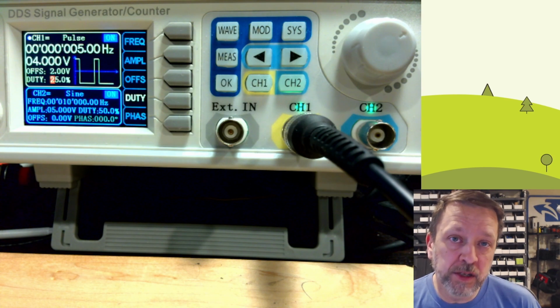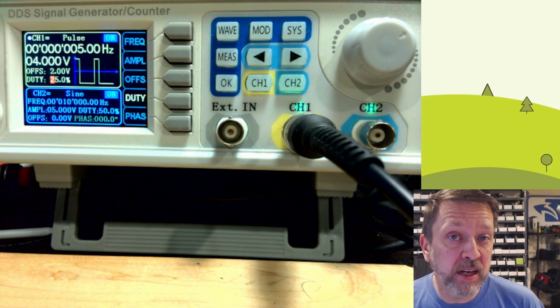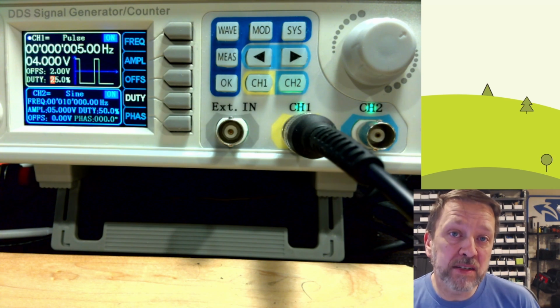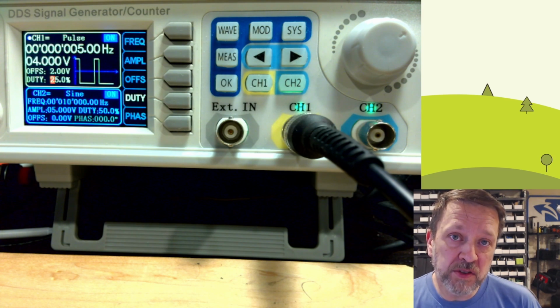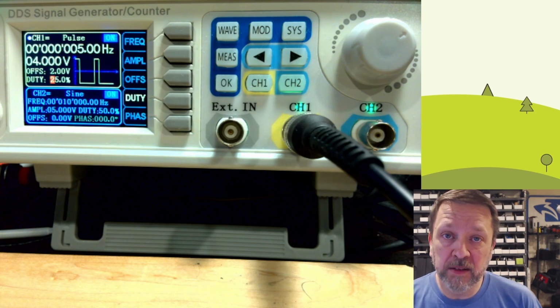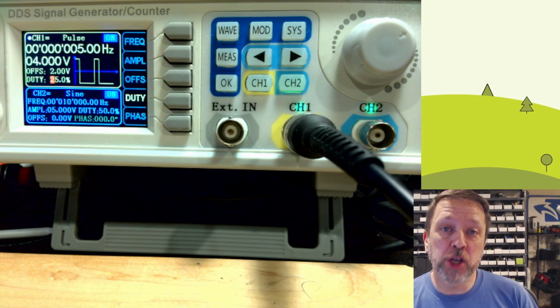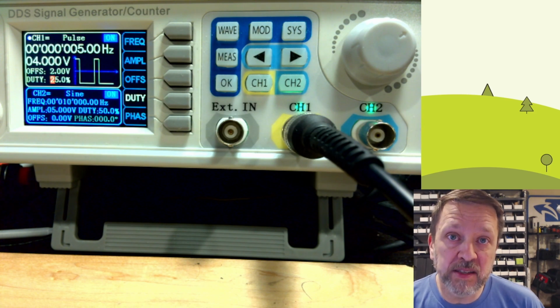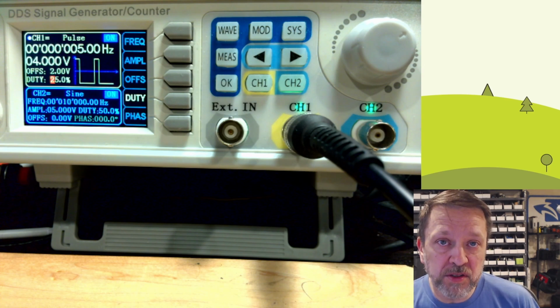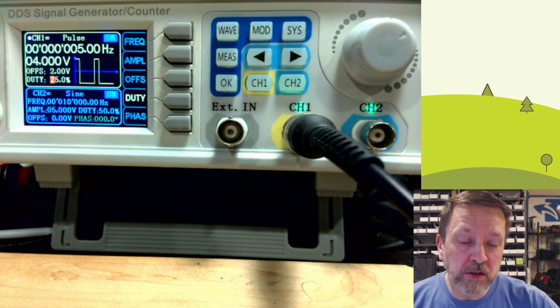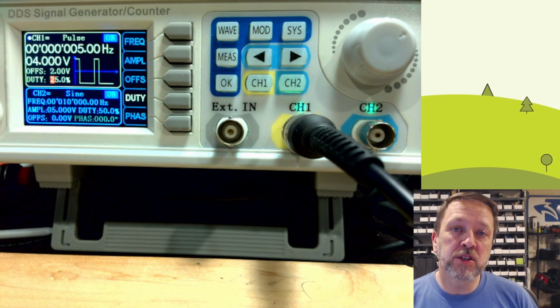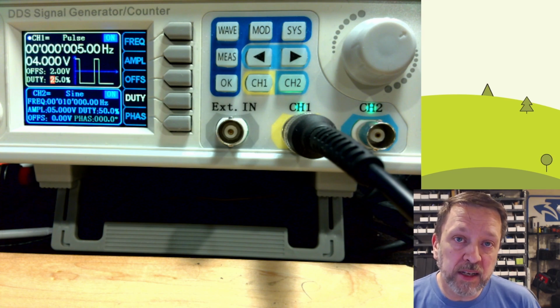Maybe I have an application that I need to handle button clicks, and I want to see how fast I can service those button clicks. How fast can I read data coming in? There are sensors that provide pulses for data, an anemometer, so for checking the wind. Basically, as they spin, they give a certain number of pulses per second, equating to a certain wind speed. You can use this to simulate one of those sensors. So you can adjust this to give the edges that you want. You can adjust it for rising and falling.